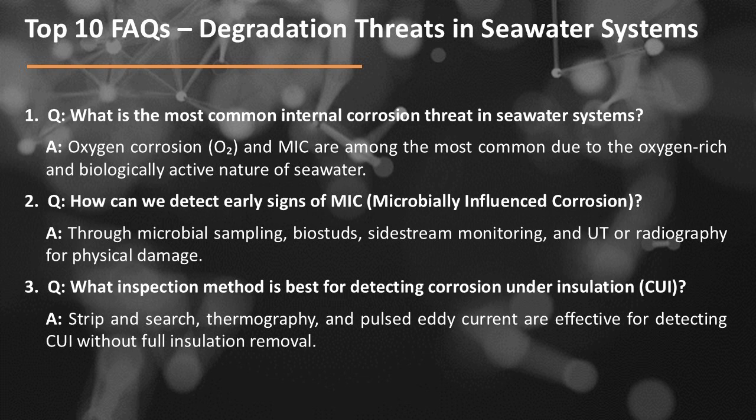Question number 3. What inspection method is best for detecting corrosion under insulation or CUI? Answer: strip and search, thermography, and pulsed eddy current are effective for detecting CUI without full insulation removal.